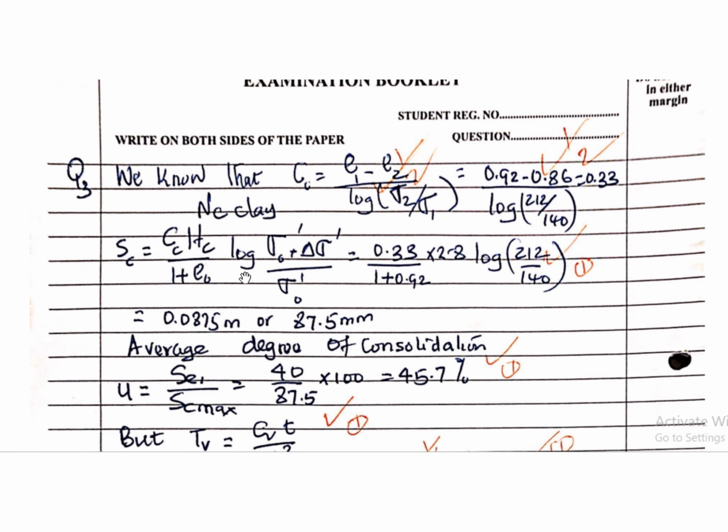So anyway, the point is this formula is different whether the soil is normally consolidated and remains so after the additional load, or is over consolidated and remains over consolidated after the additional load, or is initially over consolidated and crosses over to normally consolidated after the additional load. But the question is very clear, so this is what we do.